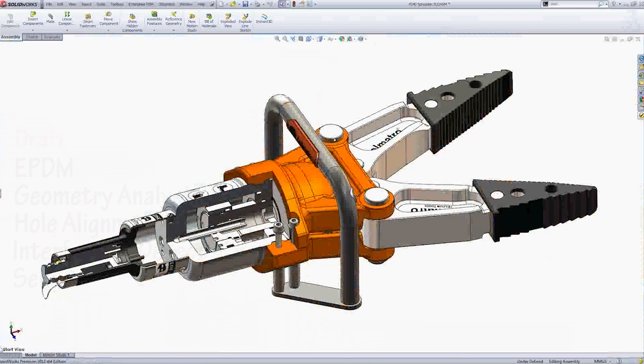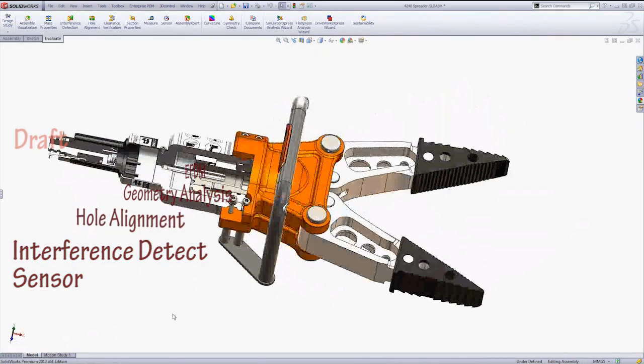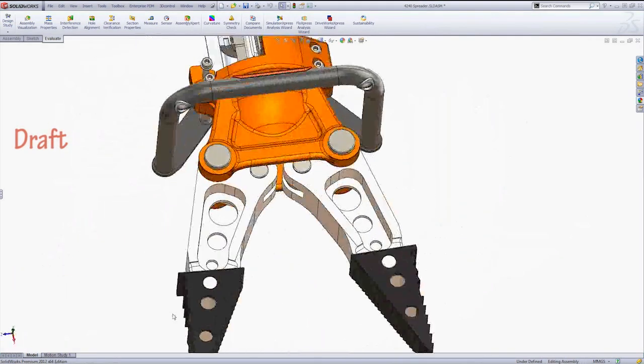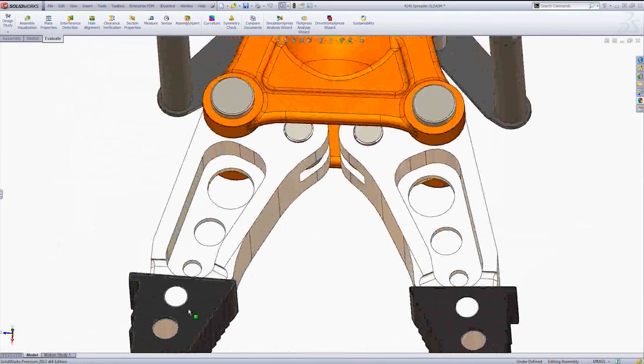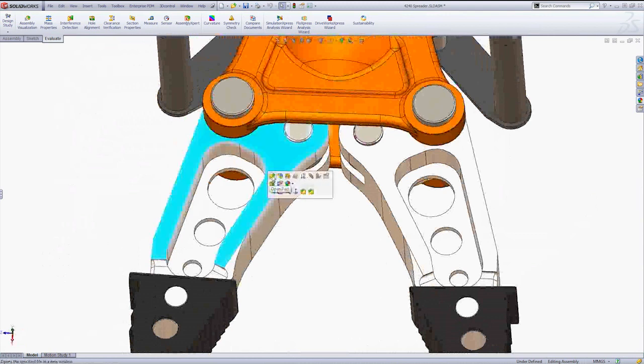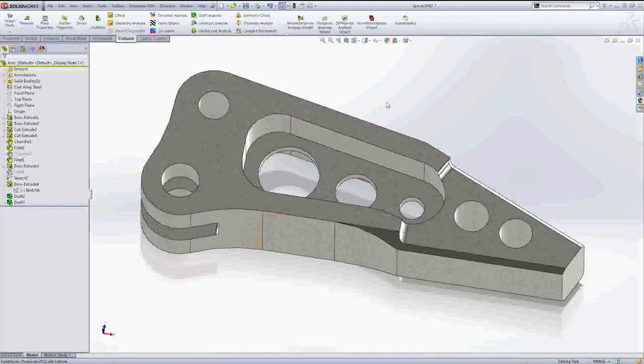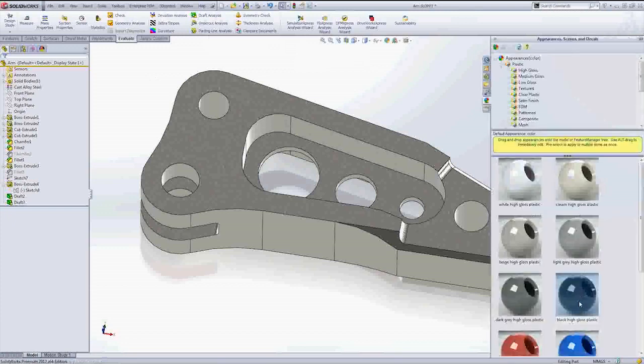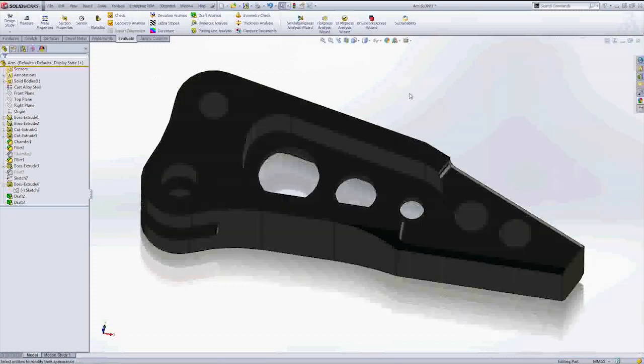When making plastic parts, draft can be a big issue. Perhaps we want to try making this arm part out of plastic, but will the geometry work in its existing dimensions? Let's find out using the Draft Analysis Wizard within SolidWorks. We can run a draft analysis on a part if we want to see if it can be made out of plastic instead of machined out of metal.